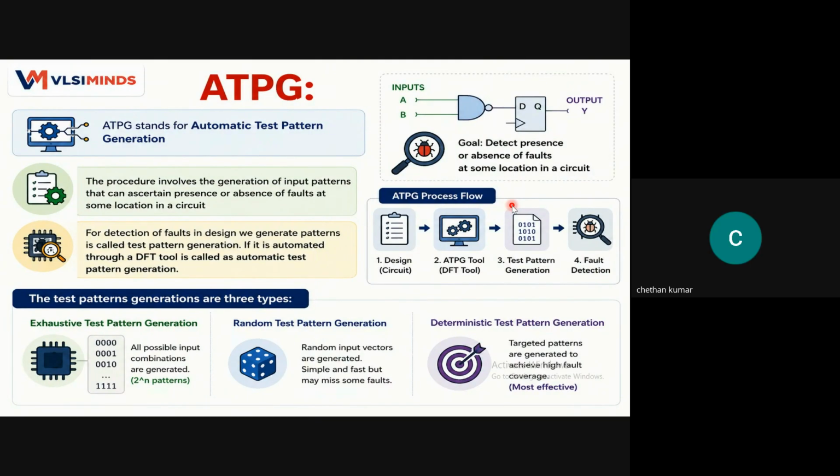So now let us move on to the ATPG. We have inserted the flip-flops and connected them in different scan chains. But how to validate whether these connections are proper or not? As I mentioned, we have to test them, and to test that, we need patterns. As we discussed in the beginning, if it is a two input AND gate, we need 4 combinations, that is 0 0, 0 1, 1 0, and 1 1, to check it's functionally working.